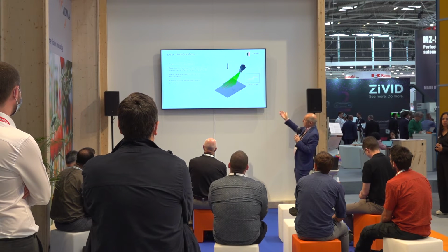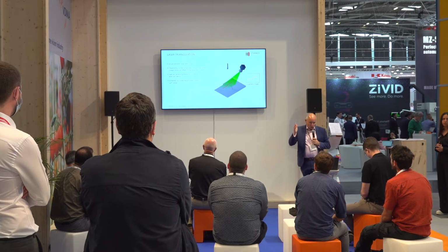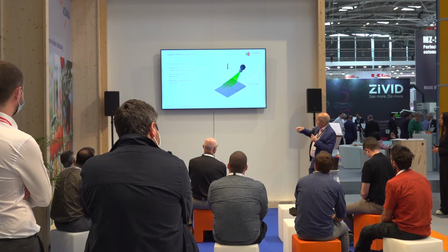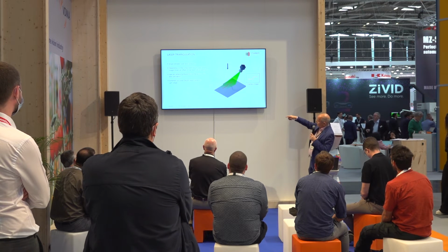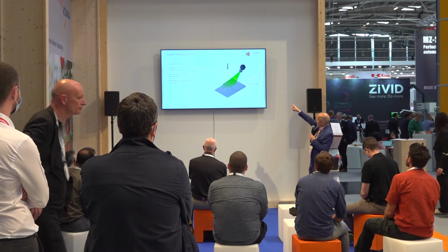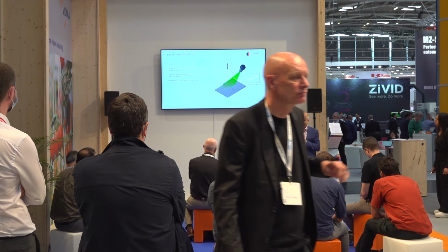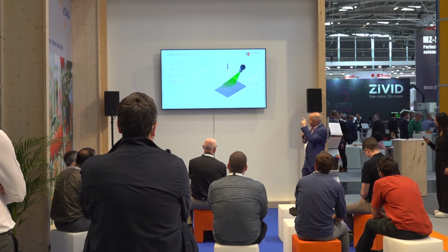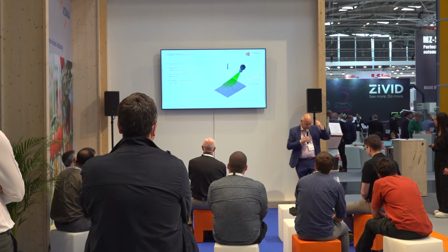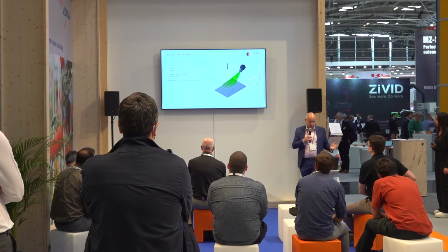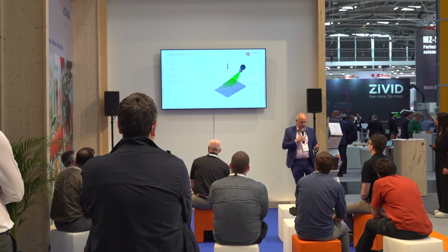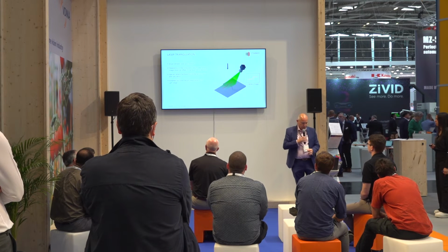And depending on the setup, geometry of it, we actually get a distortion. So as the laser goes over a boundary, we actually get a step into the camera, and we can then measure that height by that data. So the displacement of the object to that laser line gives you a profile.